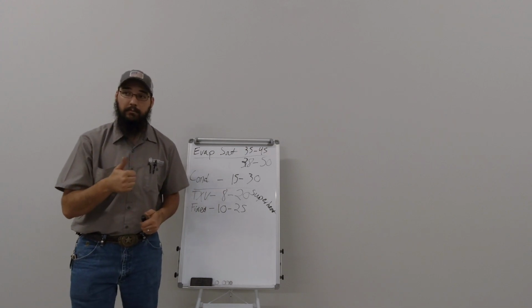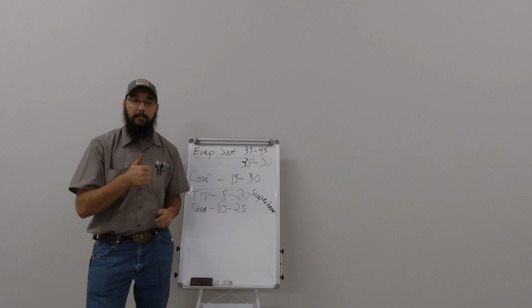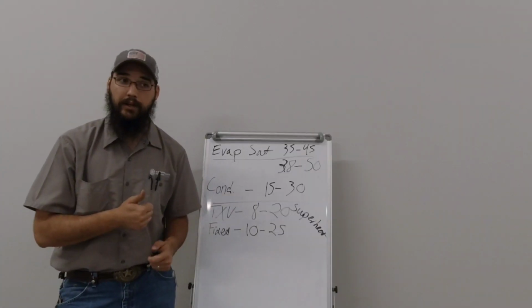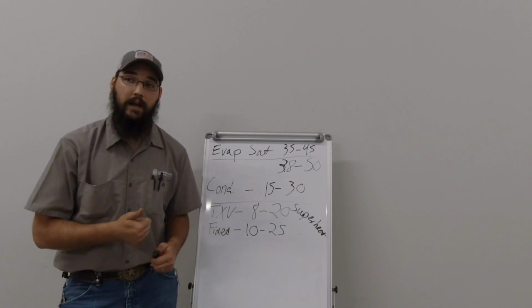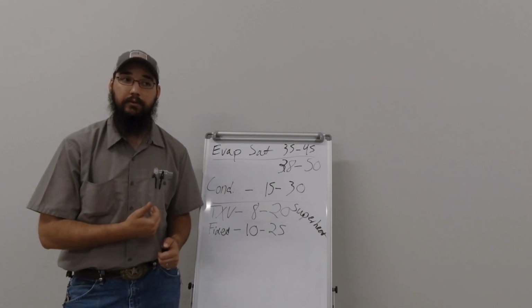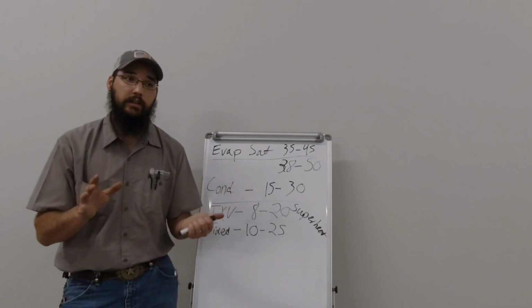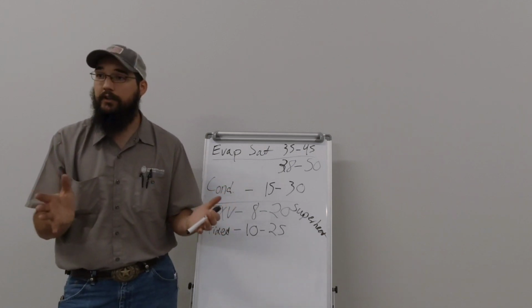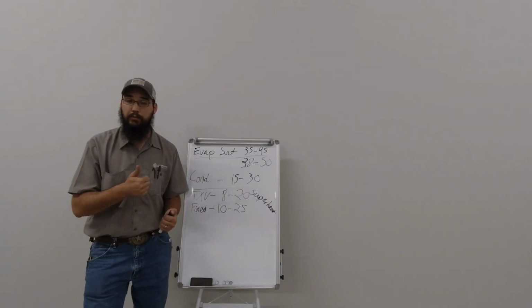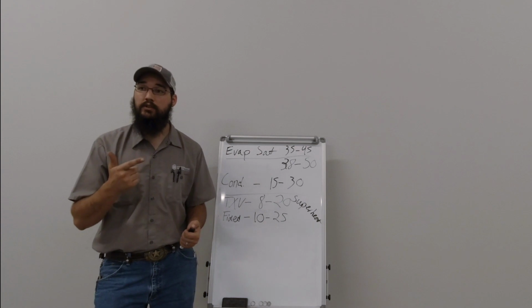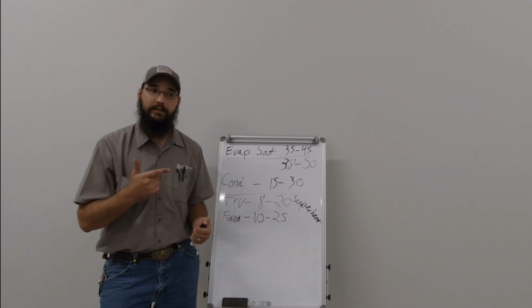So we start compressor 1, we check it, we calibrate everything. When I'm calibrating that compressor on this IntelliPack, I'm intentionally shooting these values high. So if I get a 20 degree superheat, I'm happy with that. Say I've got a 75 degree return air coming in, right? Let's say the humidity is 50%. Let's say we've got a perfect return condition. 20 degree superheat, I'm perfectly happy with. Next step, I'm going to bring on circuit 2 compressor 1 and test it.